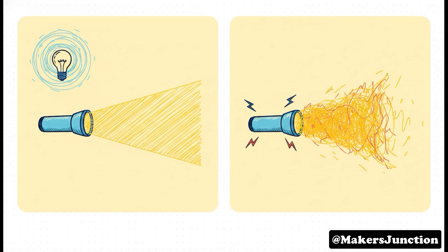I always use a flashlight analogy for this. Directivity is all about the shape of the beam. How tightly are you focusing that light in a specific direction compared to, say, a bare light bulb shining everywhere? Gain, on the other hand, is the actual real-world output in that direction because it factors in the physical efficiency losses and the impedance mismatches of the flashlight itself. So directivity is the ideal shape, but gain is the messy, real-world reality.